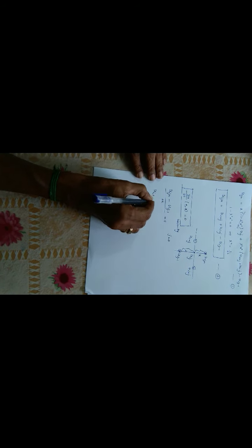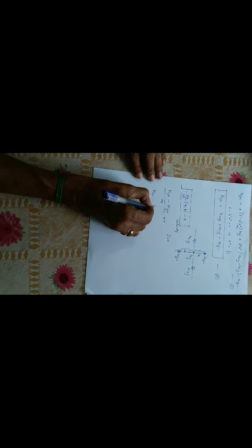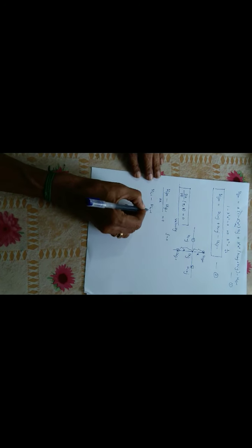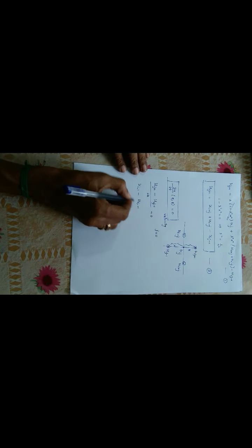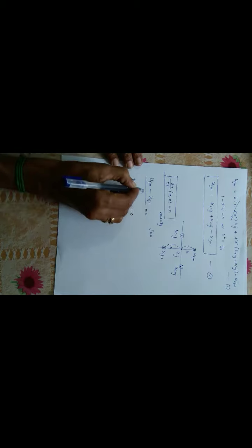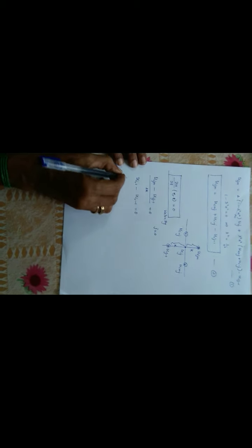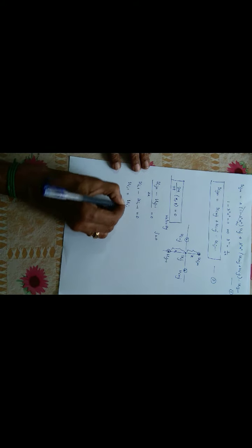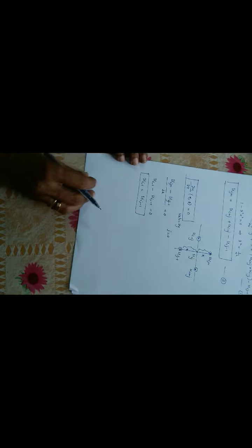Because for better understanding, minus u(i, -1), otherwise this looks like u(i-1). So in order to avoid confusion, I have separated with commas, equated to 0, I cross multiply, so therefore you will get u(i, 1) equal to u(i, -1), which is the outcome of this velocity boundary condition.